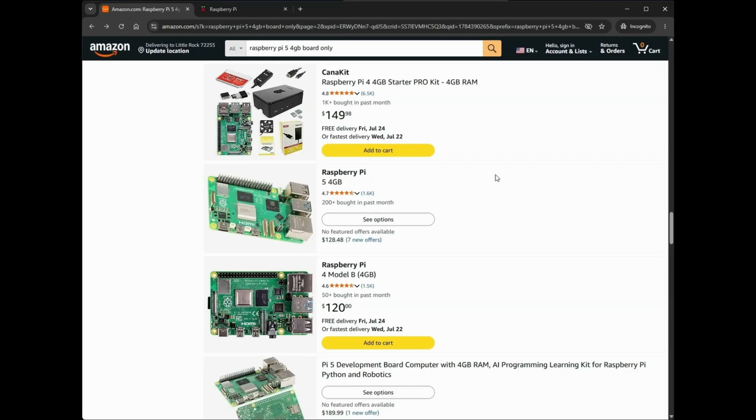Now, you have 2 options when you're looking at the Raspberry Pis. You have a Raspberry Pi 4, the 4 gig model, and the Raspberry Pi 5 with the 4 gig model. I wouldn't recommend going less than 4 gig, especially if you plan on using all of the features in the Indi-Allsky software. It just requires a little bit more resources to do the time lapses, do the keograms, kind of the housekeeping type things. You want to give it enough room to move around. If you go with a 2 gig model, you're going to start constraining the resources while it's trying to do multiple processes simultaneously.